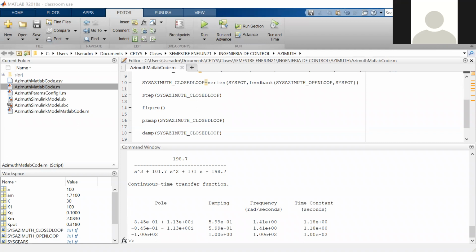That's why we talk about damping ratios between 0.4 and 0.8. You usually wouldn't want an overshoot of more than 18%. An overshoot of more than 20% might be problematic for large values, so you're usually working in that range.